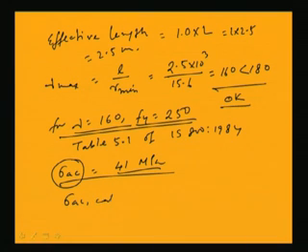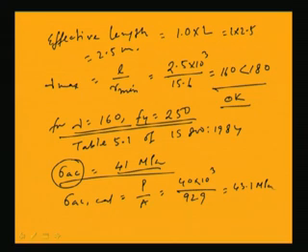So, allowable stress we have. Now, let us find out the calculated stress. Sigma AC calculated means the developed stress, that will become basically P by A. So, P is 40 into 10 cube, this is 40 kilonewton, and area is given 929. So, that will become 43.1 MPa.